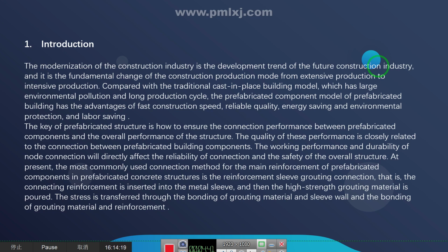That is, the connection reinforcement is inserted into the metal sleeve, and then the higher strength grouting material is poured. The stress is transferred through the bonding of grouting material and sleeve wall, and the bonding of grouting material and reinforcement.